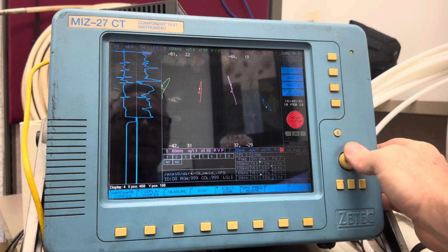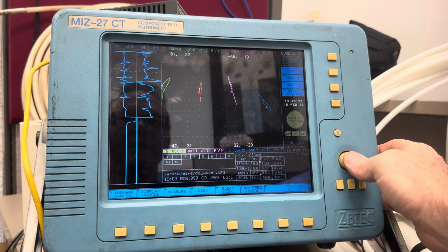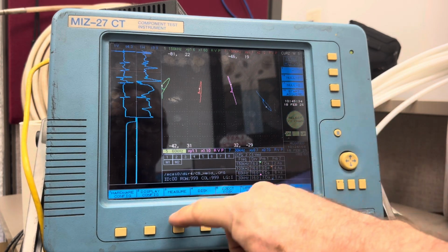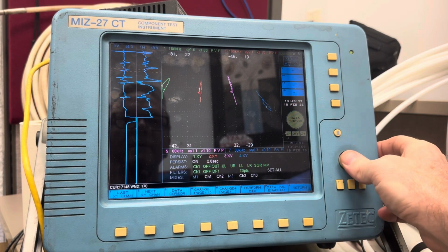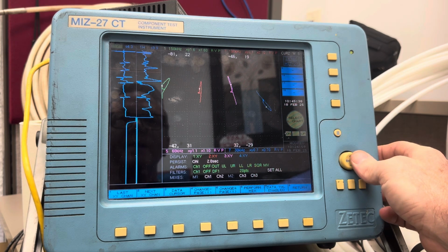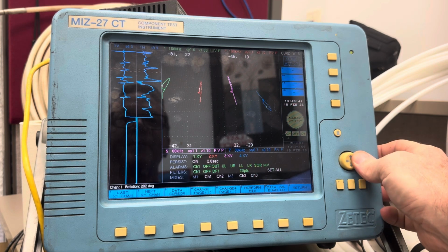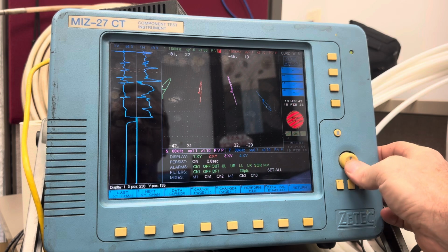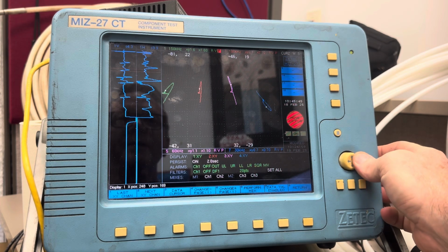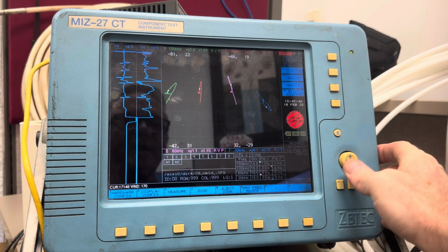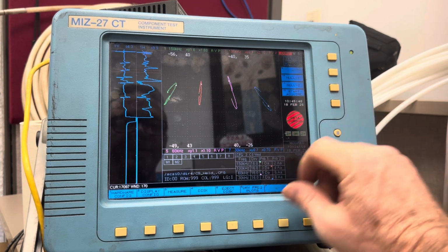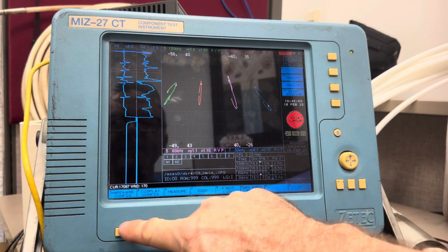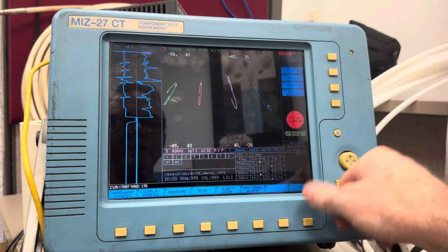You think this is bad? Wait till you analyze array probe data. There you're nulling constantly. It's very balance specific analysis. If you don't balance enough and in the right spot with the array probe, you miss flaws. So just because it's array doesn't mean it's easy. Analysis is hard, especially when you're doing tubing.